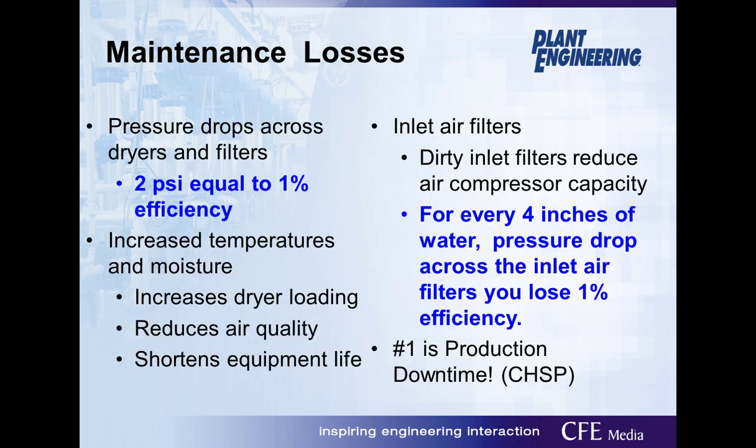So again, it should be no different than your production equipment. And why? Because the maintenance losses are huge as far as cost. We already talked about pressure drops across filters. That 2 psi equals 1% efficiency goes into real cost when you start talking about main filters. And then again, increased temperature and moisture. It increases the loading, reduces quality, shortens the life of the equipment, and just costs more money in general.